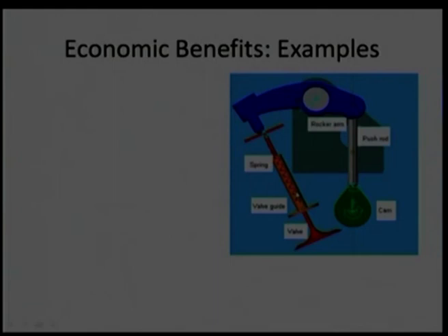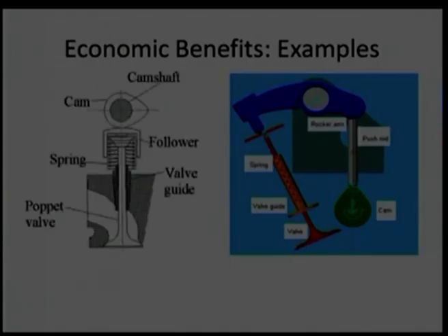So, we can find there are a number of tribo pairs, say valve and push rod, where there will be some friction, there is a mechanical contact, there is a load applied and there is a relative speed. Similarly, the contact pairs are push rod and rocker arm and shaft, rocker arm and valve, and valve guide. So, there are too many tribo pairs, and almost every tribo pair causes some friction losses. That was replaced with the overhead cam technology, where now there is a cam, a follower and directly the valve. So, all intermediate links have been removed.